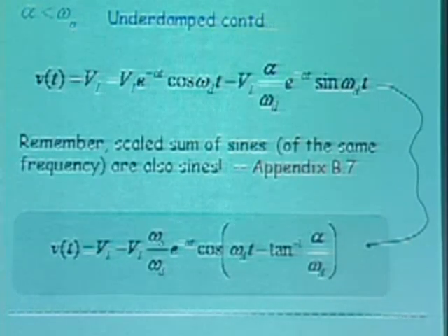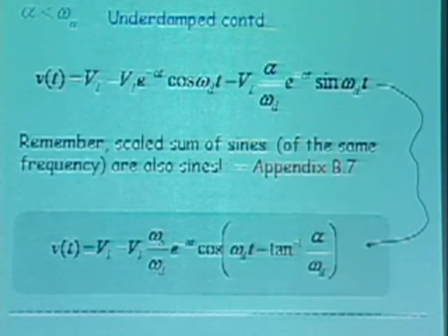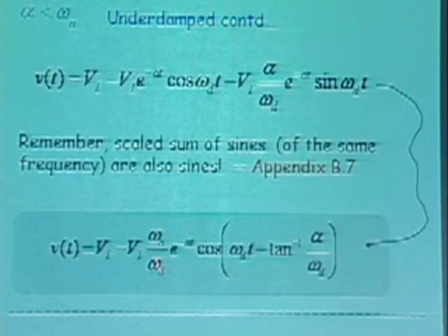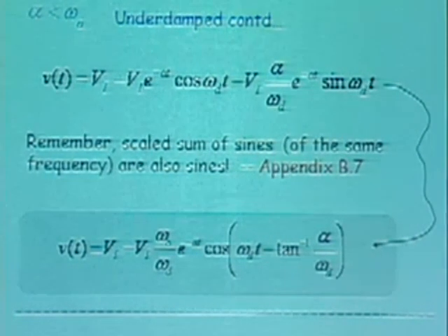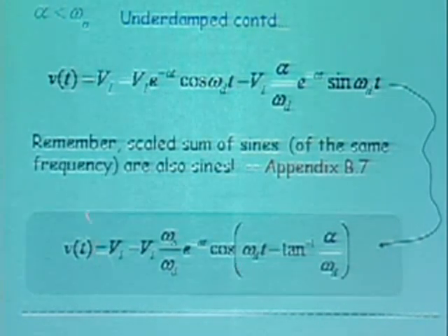Again, to pull the Feynman trick, if this alpha were to go to 0 here, then you would end up with the same expression you had for the LC situation. So let's stare at this a little while longer. There's a constant plus a minus a cosine term. So there's a sinusoid at the output, and there's an e to the minus alpha, which ends up giving you the decay you've seen before.